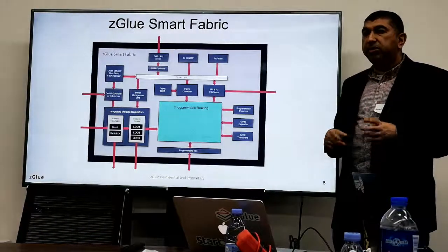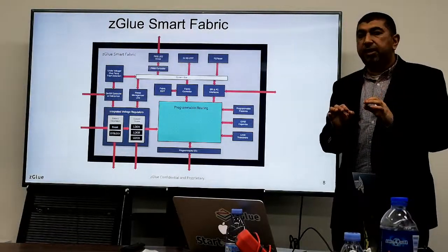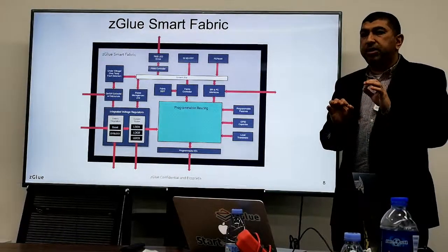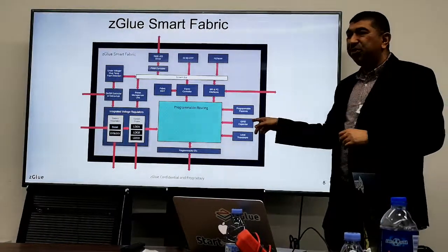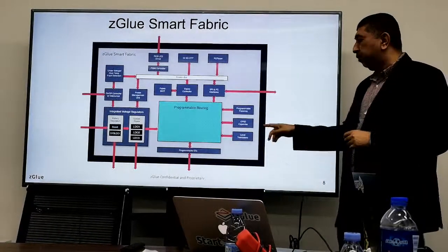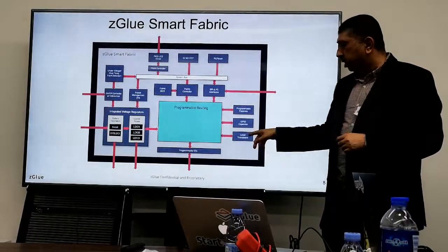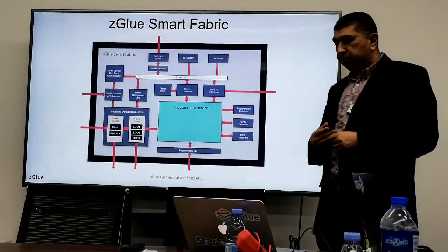You can expand GPIOs. A lot of these embedded devices have constraints because the number of GPIOs is not sufficient. So here you can use the trick that you can take one GPIO and multiplex it for different applications. And the same thing with, as we mentioned, level translators.